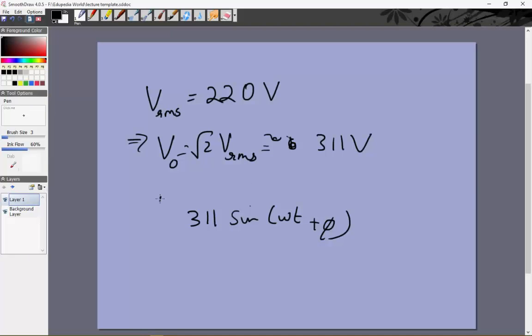Right? So again, whenever you see the voltage of a bulb or something and it is written 220 volts, you know that it's the RMS value, and that's why the RMS value is used. Unless something is specifically specified, if they tell you an alternating current with a voltage of 220 volts, that is the RMS voltage, not the magnitude, right? The RMS voltage is used to quantify this.